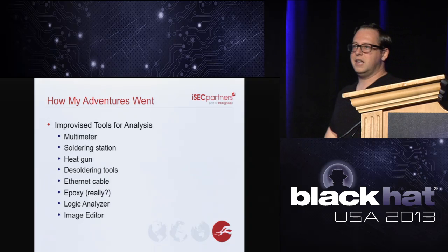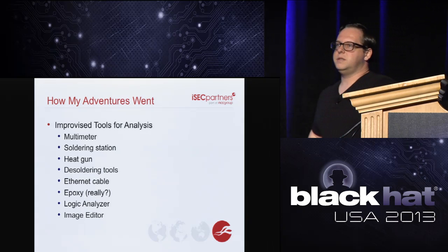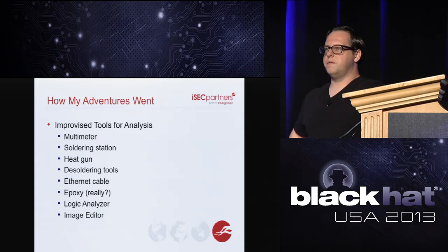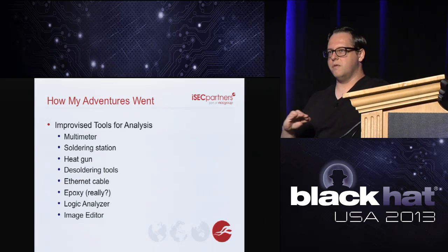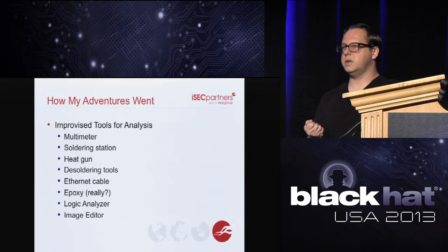Epoxy. Epoxy is quickly becoming my favorite reverse engineering tool for this stuff. I picked this tip up from a buddy of mine, Mike Warner. We would take apart USB thumb drives because the case was too big and it wouldn't fit, and then we would put epoxy over everything to keep it solid. Epoxy is not conductive, so we don't have to worry about electronics shorting out, and it's a great protector.